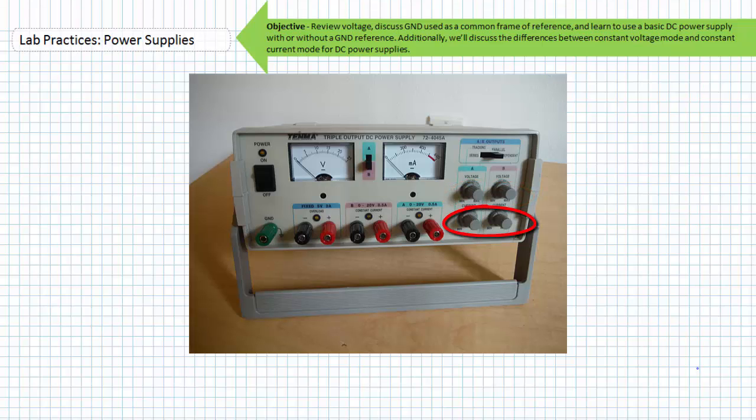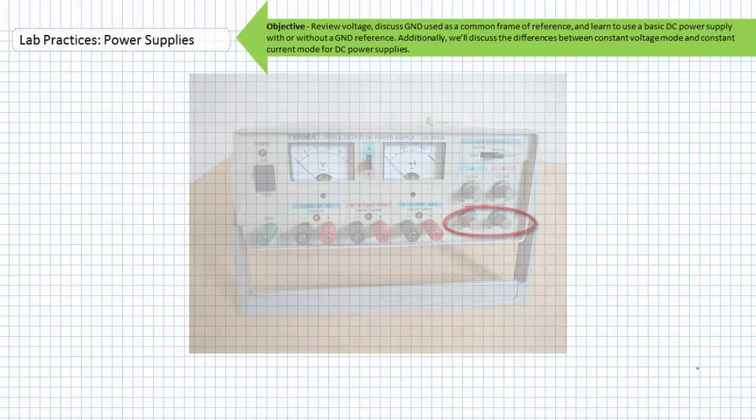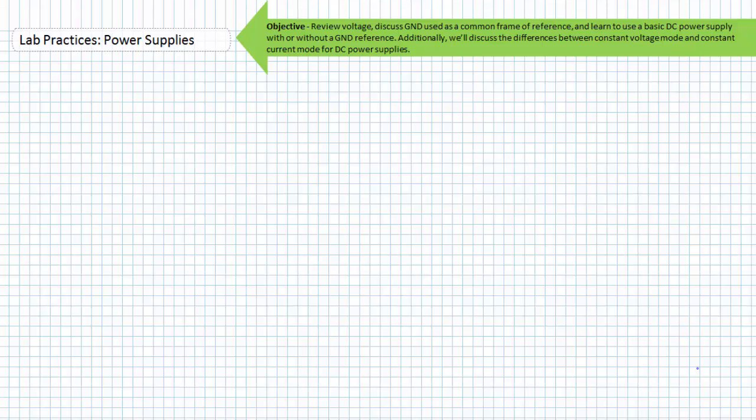If you're familiar with Ohm's law, you realize current is a dependent property of voltage and resistance. This is true. However, the current knobs simply adjust the maximum current an associated terminal set can supply. This is the current limit adjustment. The maximum current capable of being supplied by the adjustable A and B pair is 0.5 amps, or 500 milliamperes. And this value can be adjusted downwards from there via the associated current control knob.